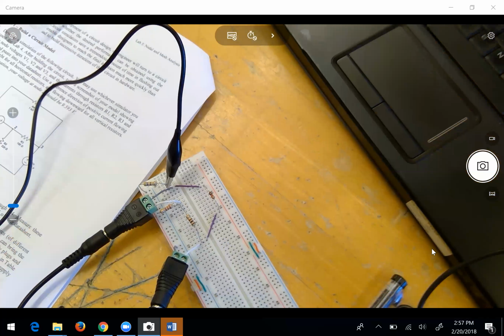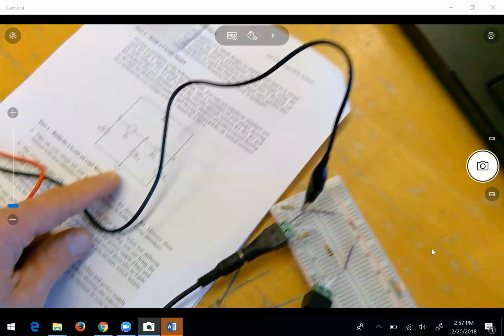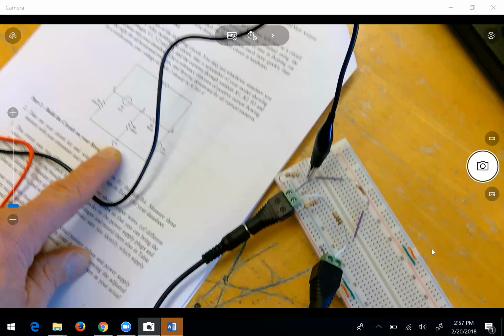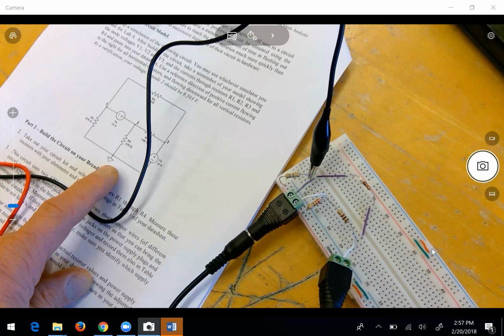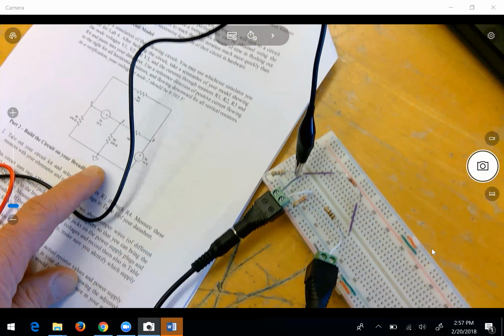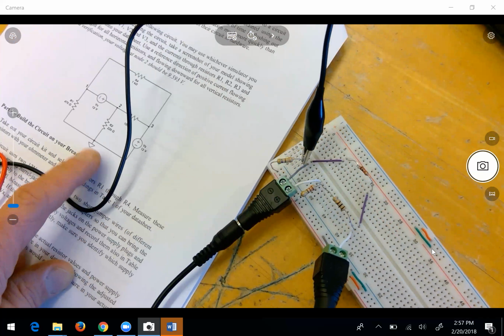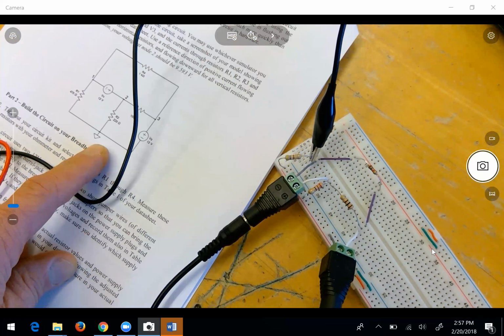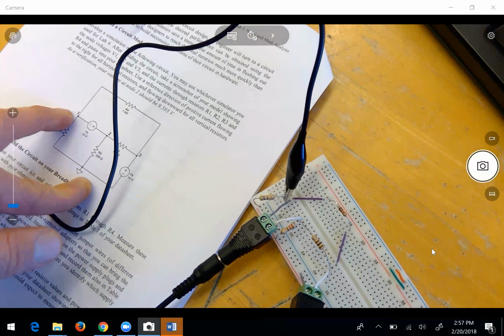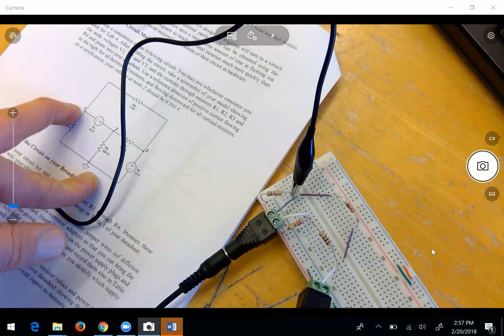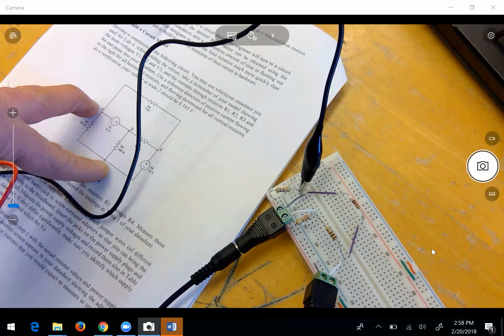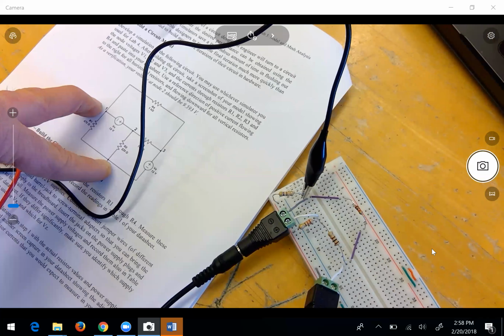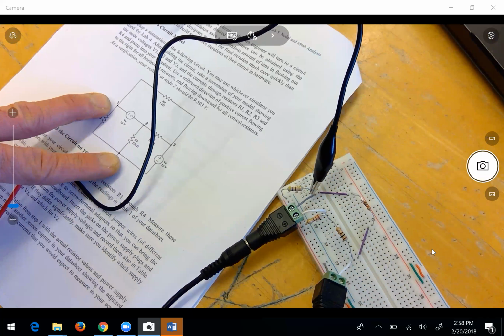What we call node voltage is relative to the reference node, which is ground. The reference node is arbitrarily chosen to be 0 volts. We don't know if it's 0 volts or not, but there's our reference node. That's what we're calling 0 volts. And when we have labeled this thing V1, that means the potential difference between this node and ground is V1 volts. That should tell you how to hook up the voltmeter. See how my fingers are arranged?